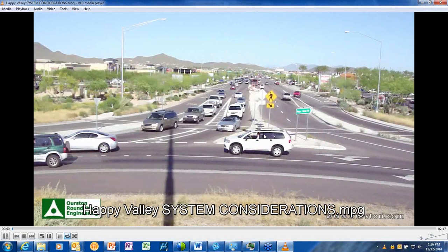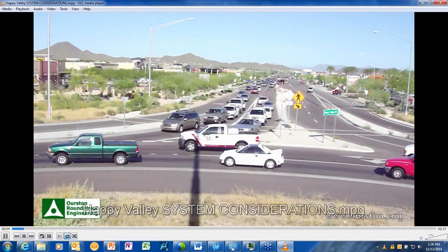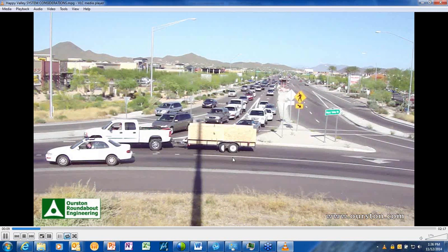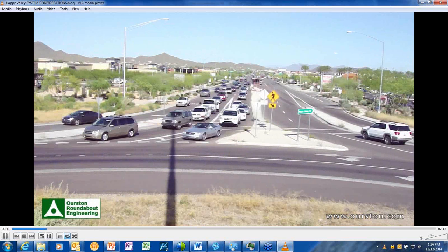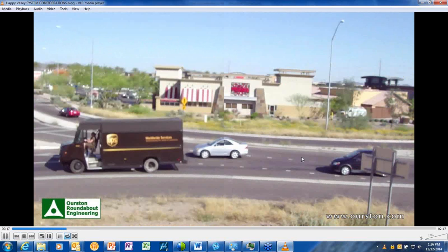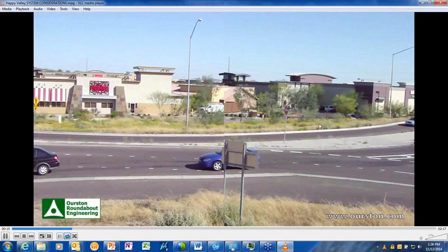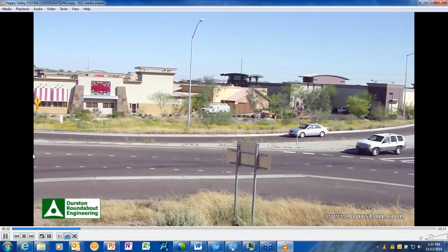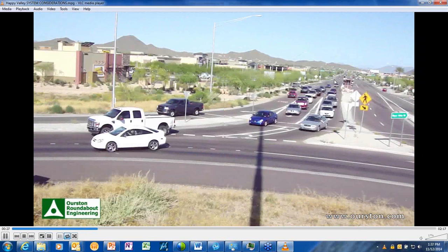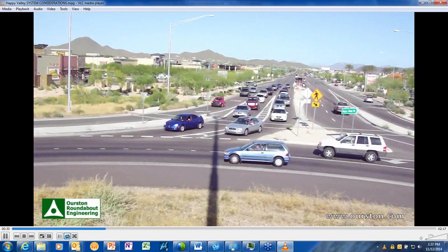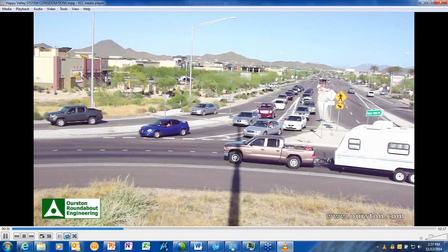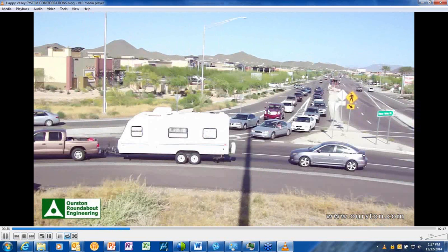So now we're looking back towards that corridor, and there comes a platoon, and there's already some capacity constraints associated with this entry. It has possibly good free flow bypass accommodation, but there's enough off-ramp traffic that there's impedance of that Happy Valley Road entry at 2 lanes wide. Now the signal has stopped the traffic from upstream. The platoon is coming through. And just in that little time when I moved the camera to the right, a lot of traffic got through the roundabout. We turned away and about 10 cars went through.